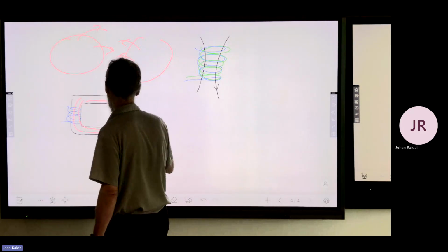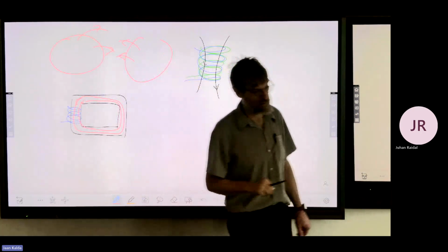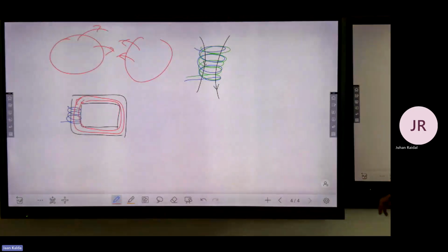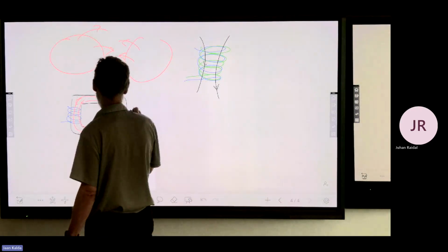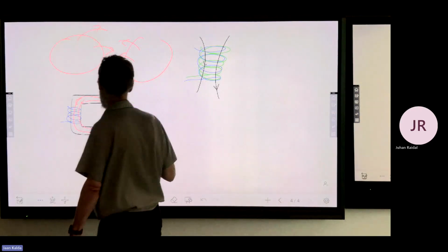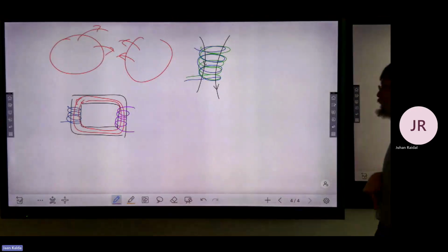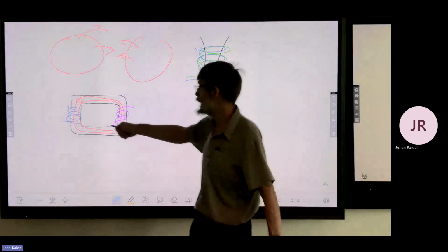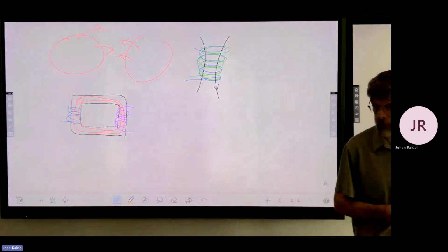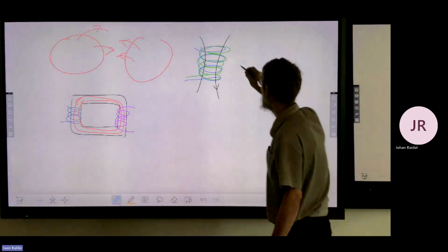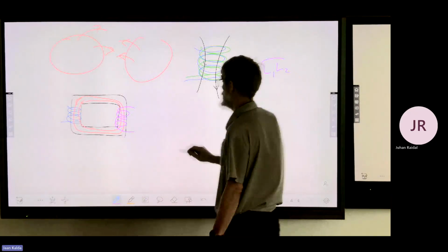So it doesn't matter too much what the shape of these currents is, but the field lines repeat the shape of the closed magnetic core, meaning that now if we put here another loop, the field lines have the same shape. And again, you can reach a situation when there is almost no magnetic field if you have opposing fluxes created by one and the other. So both here and there, M is just the geometric average of L1 and L2.